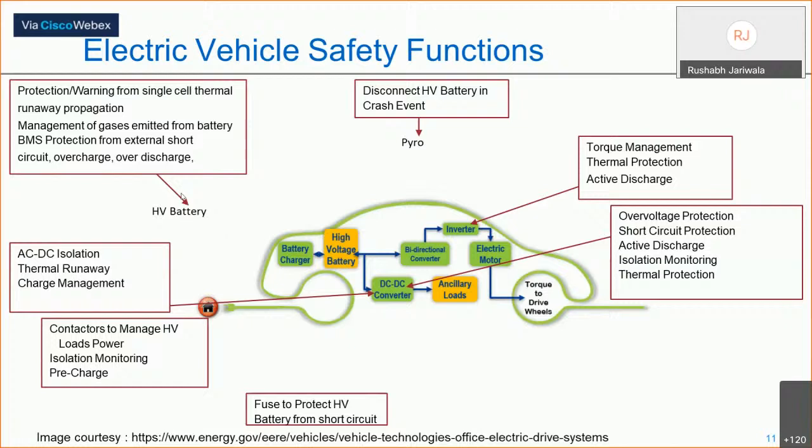The other thing, let's move to this, the DC-DC converter. Typically the DC-DC converter derives the voltage from the high voltage and then feeds all the LV, low voltage loads. That has to do with some of the radiator fans, the ones related to the console, plus powering all the ECUs and all that.